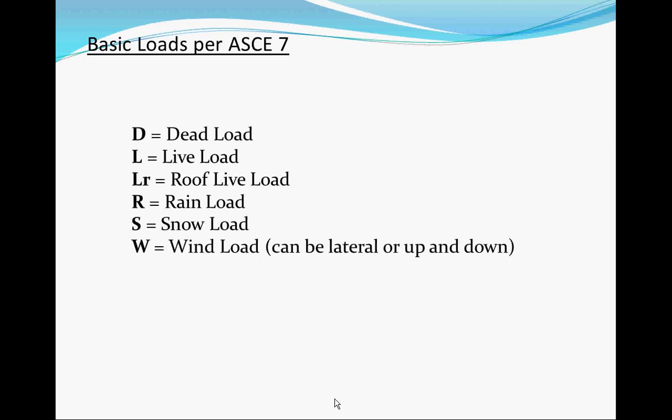And the building code has minimums for a lot of these, and you just typically go with that. Dead load is what engineers probably determine, and they add up the materials. My tile is this thick, so much weight, you assign it some value. So that's how you do the different load combinations. For earthquake load, we just determine what the earthquake load is. So that V is the earthquake load.